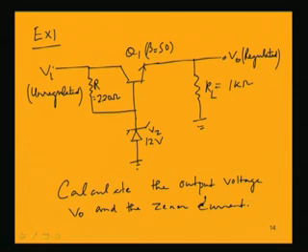So find out V0 and IZ. IZ is the current through the Zener regulator, that is this current here. These are the polarities of the Zener diode as it is connected; it should be in reverse breakdown. So now let us do this example.